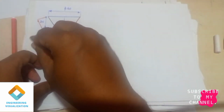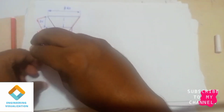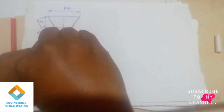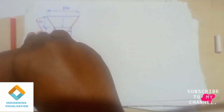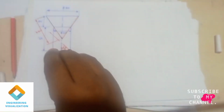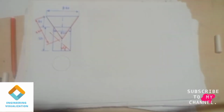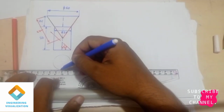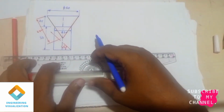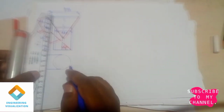So we need to project that axis downward and then we should consider the center. Here I am taking directly the center point of it. So you need to project downward that axis, take the center point and draw a circle. After drawing the circle, show the dimension. Here we will be dividing this circle into 8 equal parts.